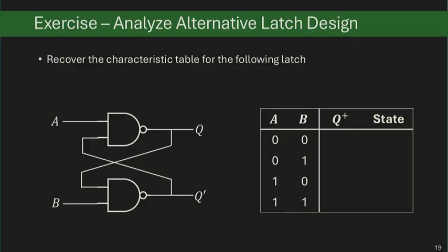Yeah, I like to do it with only the smaller characteristic table, by essentially compacting Q as part of the output and then describing it in terms of Q or 0 or 1. That saves you a bit of work. Right now, I only have to try 4 different cases instead of 8. Yes, I only use that table.